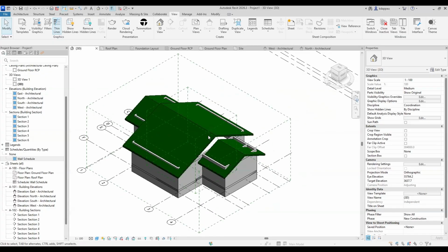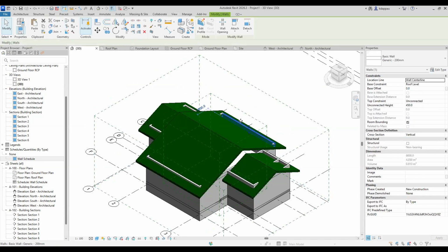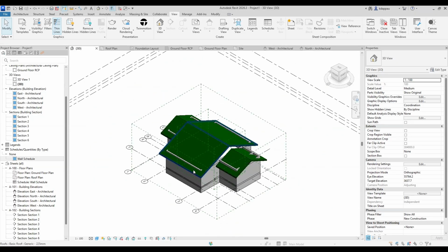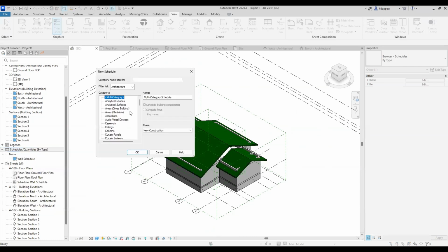For instance, let me calculate the total surface area of the roof that we've just constructed and show you something. Let me show you the roof that we've done. This roof here, and then this roof. Let me calculate the area for you, then we'll close and continue tomorrow. So I'll go to schedules again, New schedule and quantity. And I want to do a schedule for what? Roof. So I'll select roofs and do a roof schedule, then go to OK.